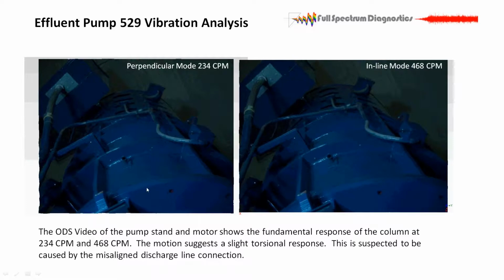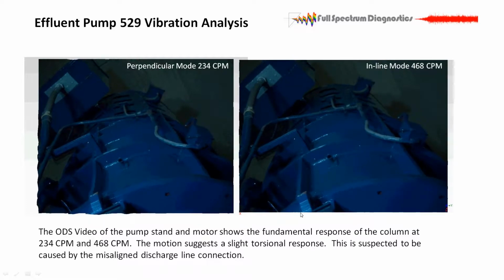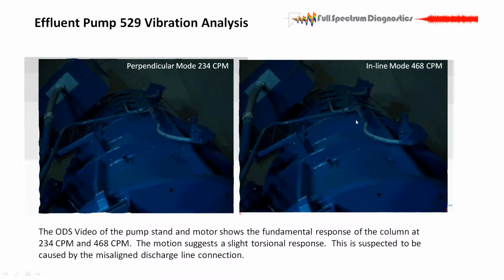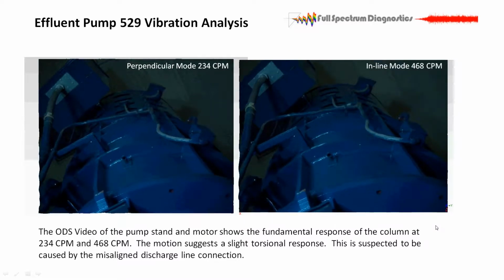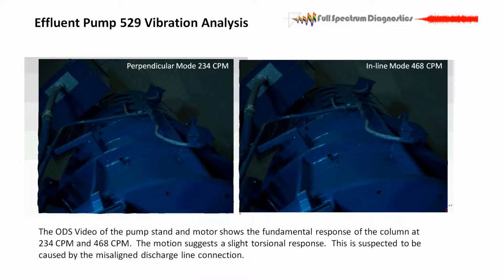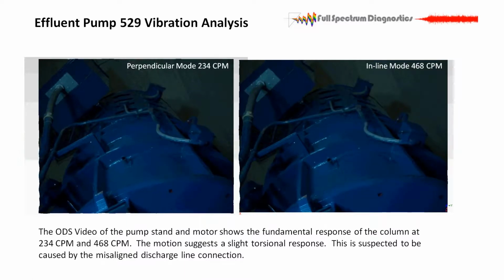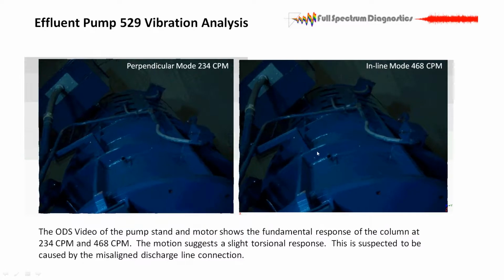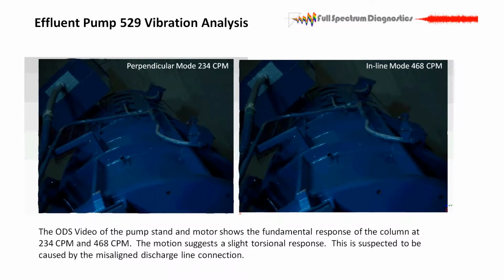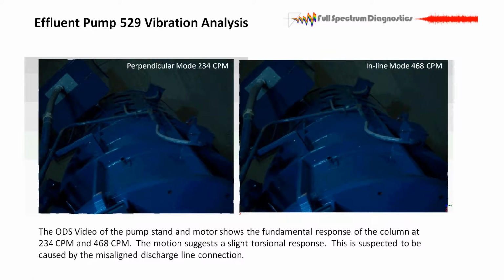What I think is going on at this point is this mode is being caused by the binding in the discharge line, and we're putting a big force in there. It's very likely that this is close to a torsional mode of the cantilevered beam structure, and we've stiffened it into the operating speed range.